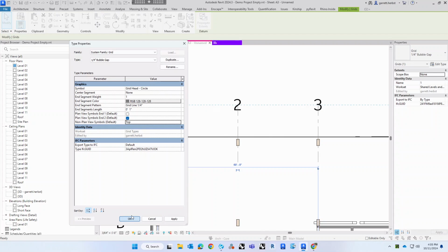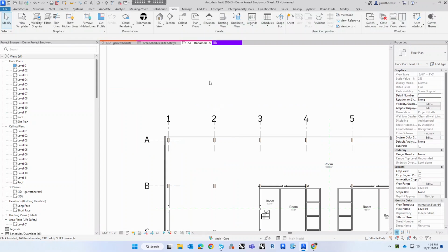So what you could do is add an invisible line at the bottom, and you could basically turn that circle into an invisible line, which is just a line that's colored white. So just be aware of that. You could turn it into a white one, and then it'll have the same parameters, the same buffer zone around it as you want. Again, all that to say that you can customize all of the families in here, including the annotation families, to be as visually aesthetically pleasing as you want.